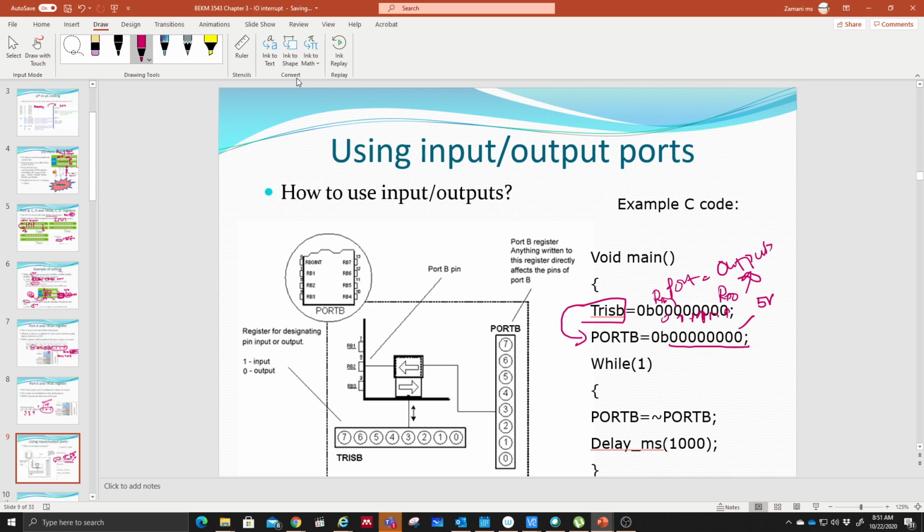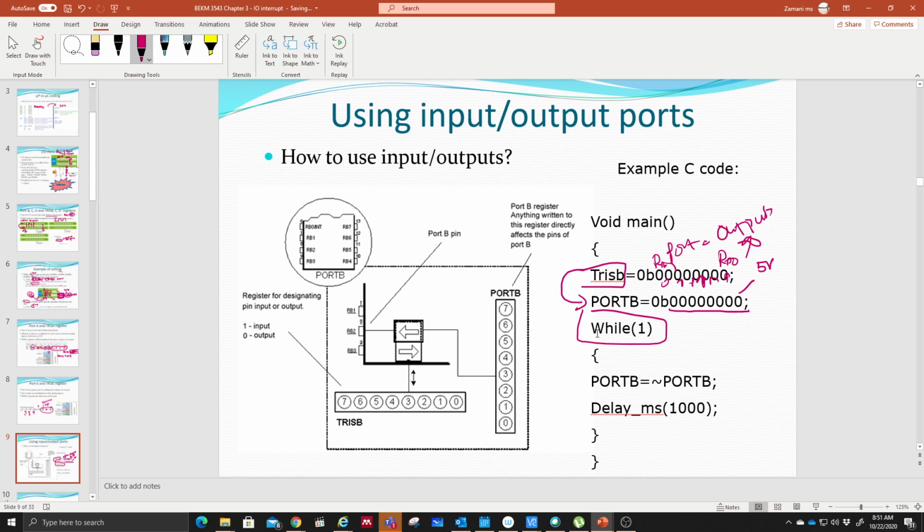So after that, it will move here. You can see that this is a while 1 loop, right? So while 1 loop, you have to put 1 over here, because this one is telling us that the looping must be continuous once it goes in. So this is only done, this is completed once only, means the program will go down, right? So once it completes this one, it goes to the while 1 loop, so it's going to loop forever here.